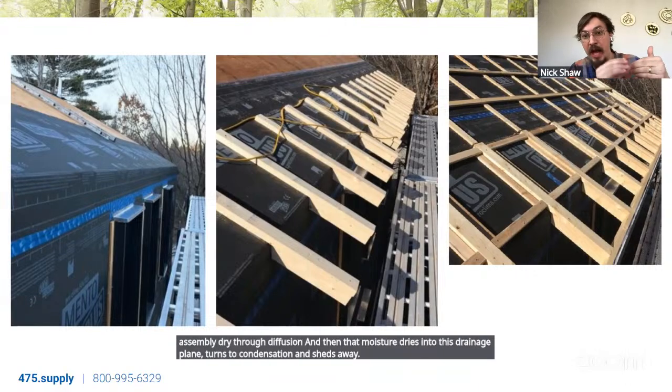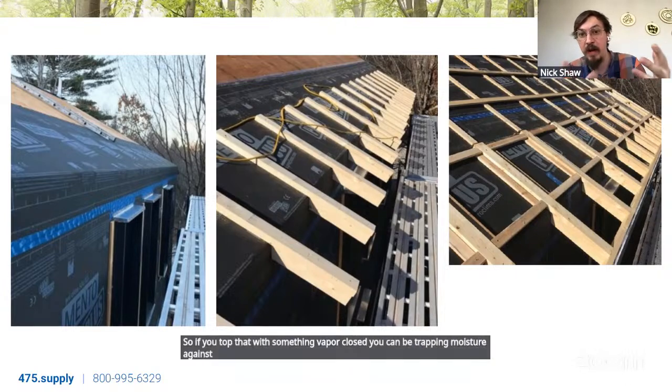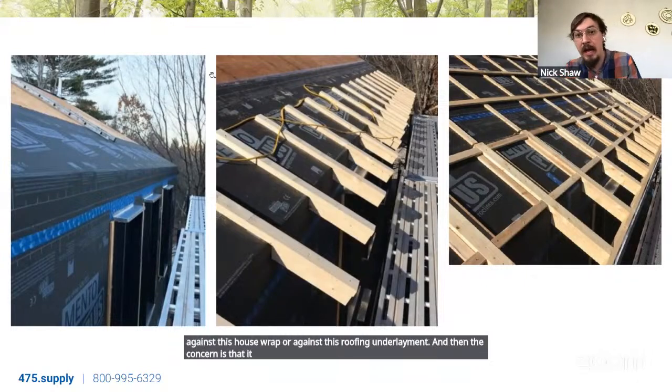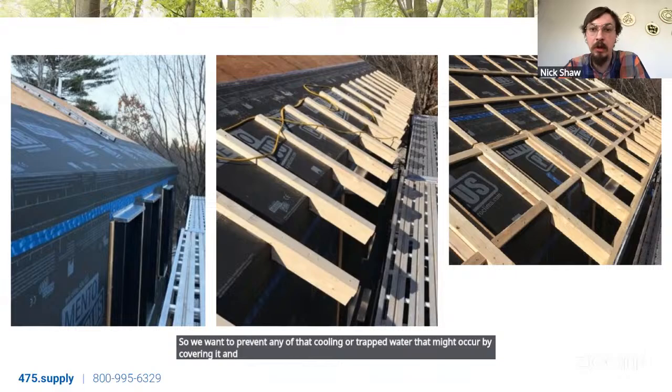So if you top that with something vapor closed, you can be trapping moisture against this house wrap or against this roofing underlayment. And then the concern is that it's not effectively draining and it's following a fastener back into the assembly. So we want to prevent any of that pooling or trapped water that might occur by covering it in a vapor closed insulation such as rigid foam.